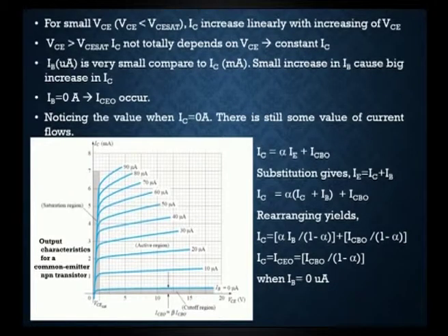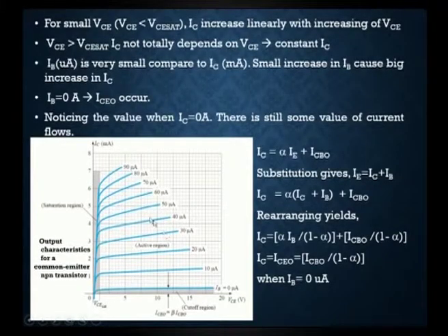So, now we move on to the output characteristics. The output characteristics are formed by plotting a graph of output current against output voltage, keeping the input current constant. For different input currents, we need to plot a graph of output current and output voltage. Output current is our collector current, measured in milliamps, and output voltage is the collector to emitter voltage. And here also we observe the 3 regions, that is the cutoff region, active region and saturation region.